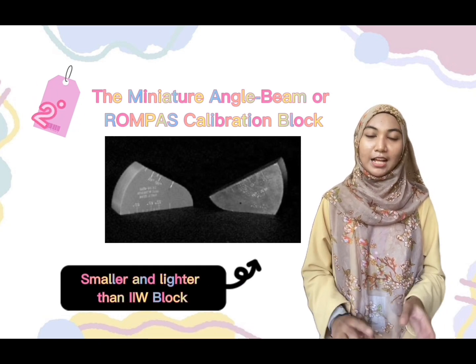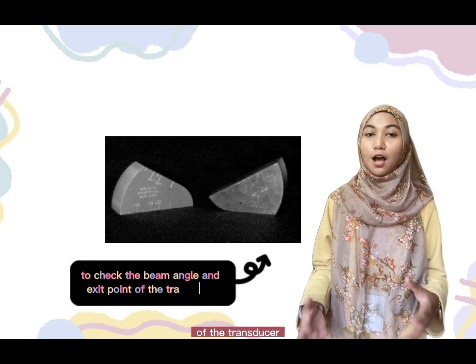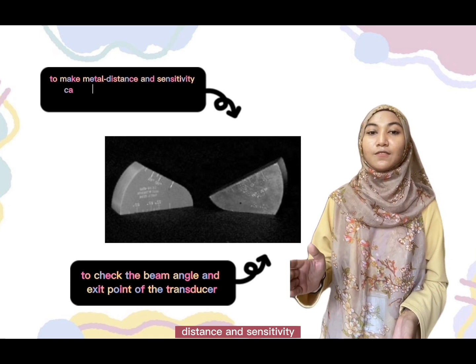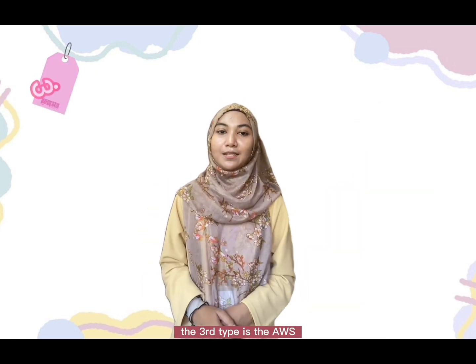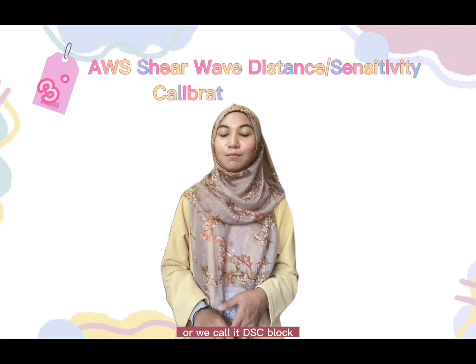The miniature angle beam block can be used to check the beam angle and exit point of the transducer. The block can also be used to make metal distance and sensitivity calibration for both angle and normal beam inspection setups. The third type is the AWS shear wave distance sensitivity calibration block, or what we call the DSC block.